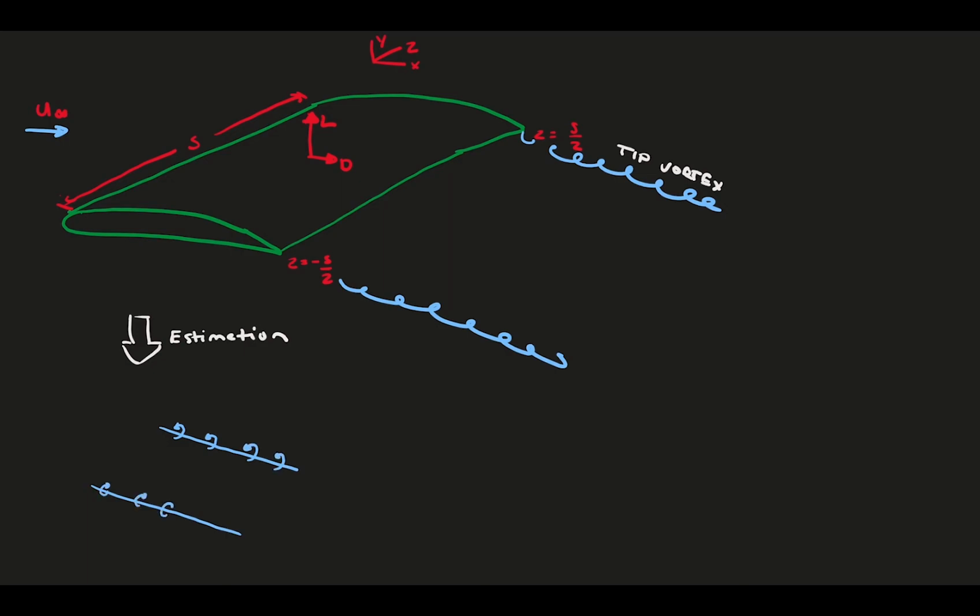However, the Helmholtz vortex theorem tells us that these vortices cannot just start out of nowhere. But instead of using a surface like the wing, we're going to connect them with something called a bound vortex. Here, the vortex is called a bound vortex because it is bound or represents a boundary replacement. The tip vortices are called free trailing vortices because they exist and follow the flow. This connection of vortices, which looks somewhat U-shaped, is commonly referred to in fluid dynamics as the horseshoe vortex.